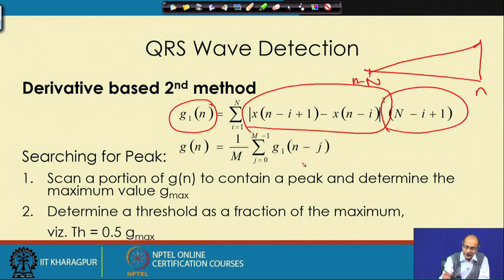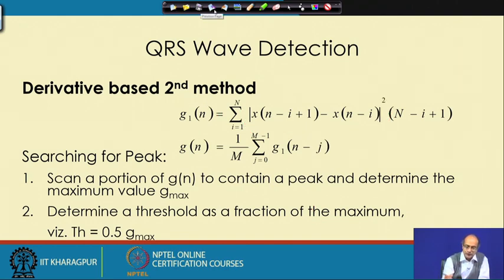And after that we take a threshold that is data driven. Okay. So, how does it become data driven? The first operation is that for this signal G, we look for the maximum or the peak, and we mark them as G max.